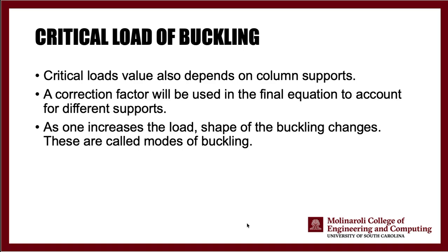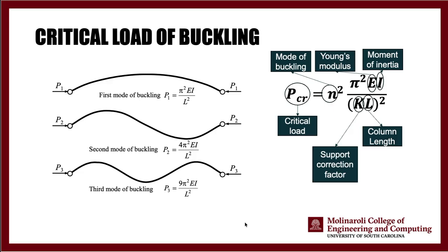And as you increase the load, you have to keep in mind the shape of buckling might change. These shape changes are called modes of buckling. That is not an important part of the discussion for us, but the idea simply is first mode of buckling, your column is going to buckle like this. Second mode of buckling is going to buckle like this. And the third mode of buckling, you are going to see a wavier pattern and so on and so forth.